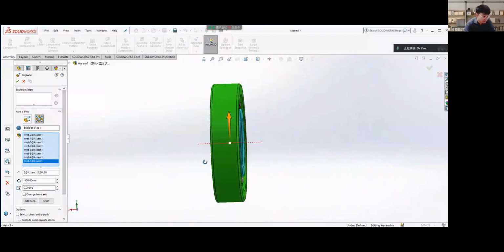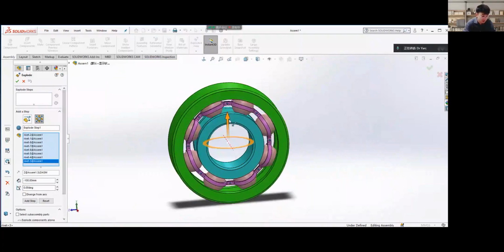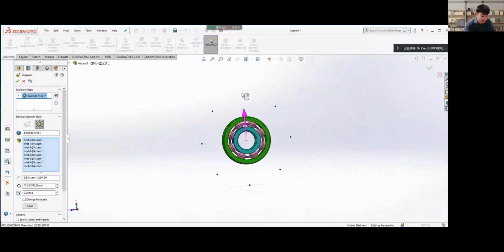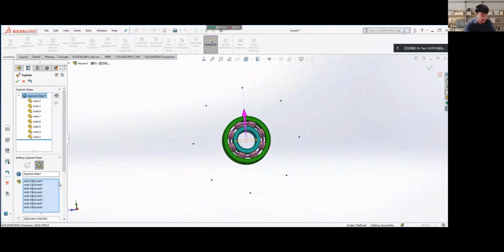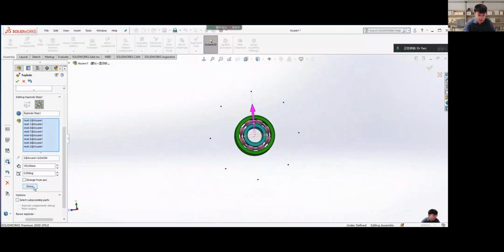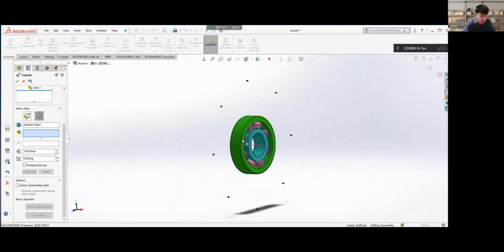All right. For this one here, see that direction is coming to the outside of the ring. If you pull this and hold this and put it out, see that? It becomes like it's separated like a circle, right? And it's symmetrical. Here you can just give a dimension for it, the export distance. Just give it 100. I think it's good. And don't forget to press the down button right here. Now you can just go to the next step.